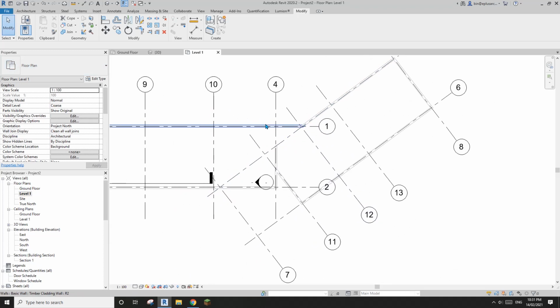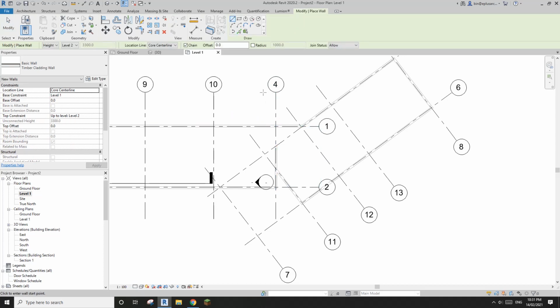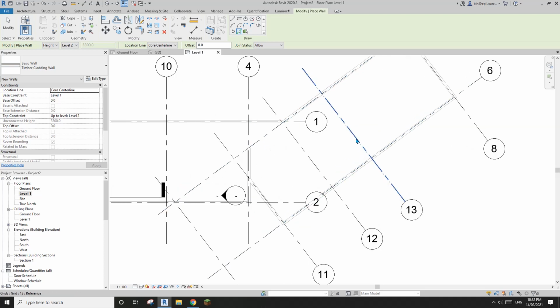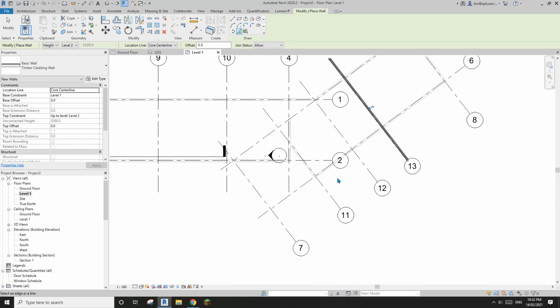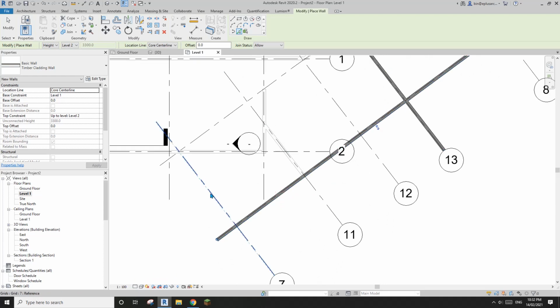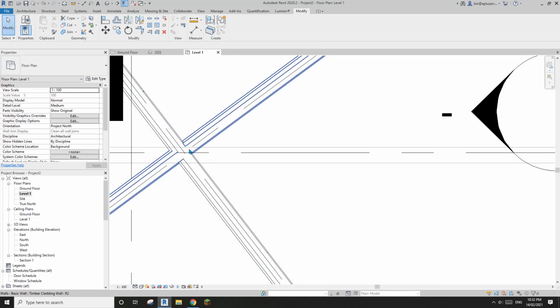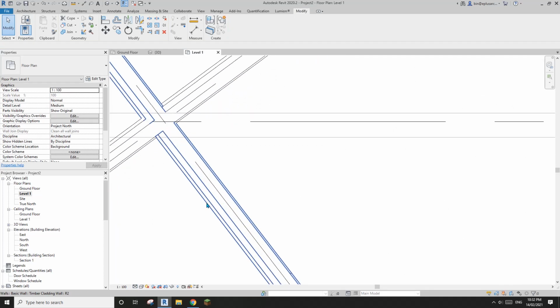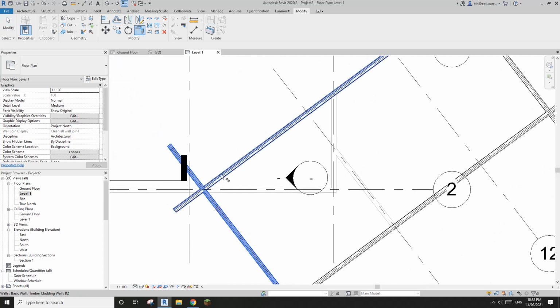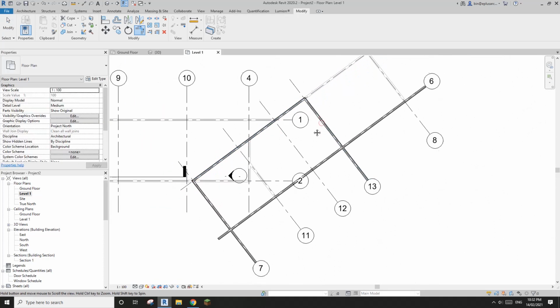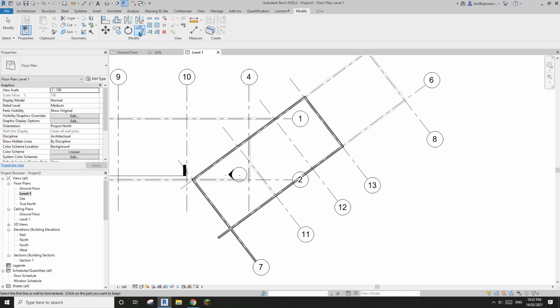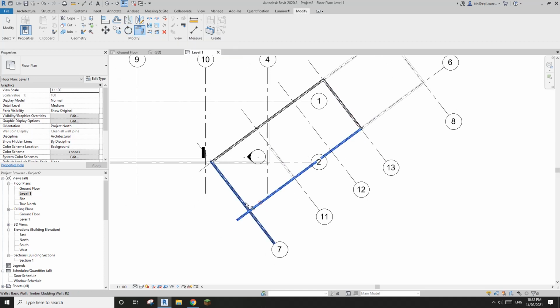So you can select the wall, CS, create similar. Let's pick line and pick this grid. Start from here, and make sure this is on the exterior side, and pick this one, and this one, and this one. Also change the detail to medium, so you can see and make sure they are correct. Okay, so structure, external cladding, right? Trim, TR, trim. Trim all, trims here, TR, trim.